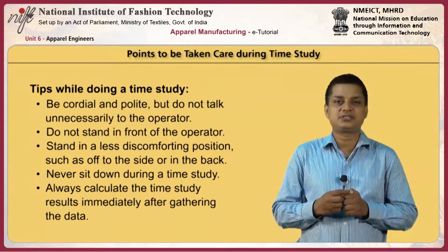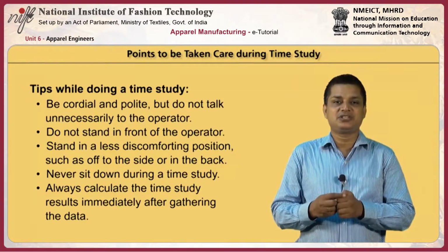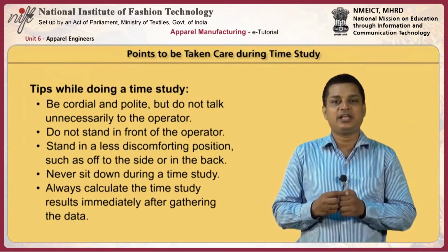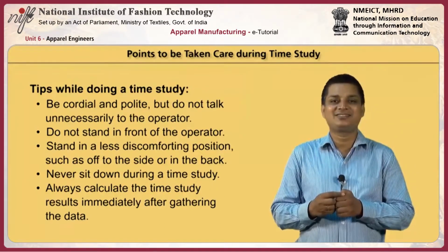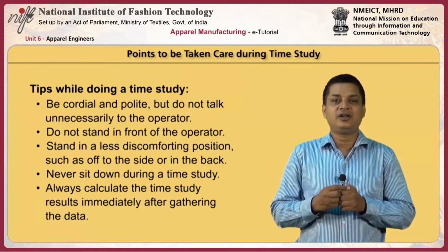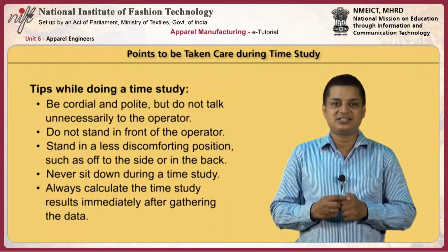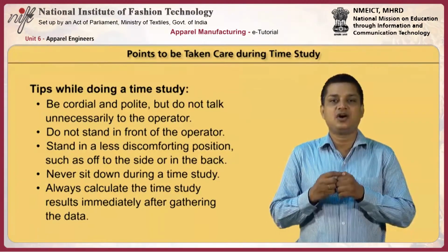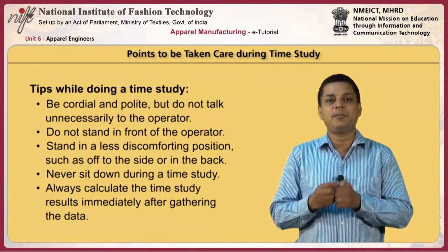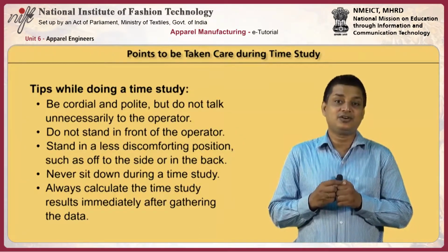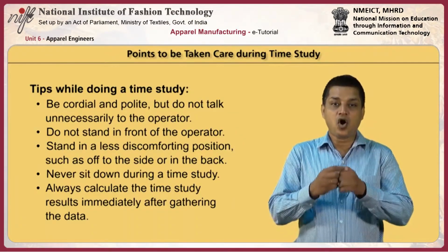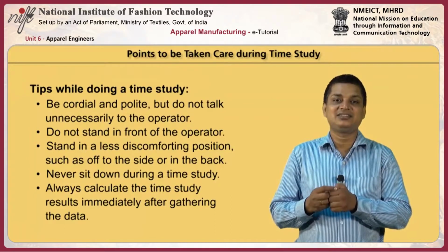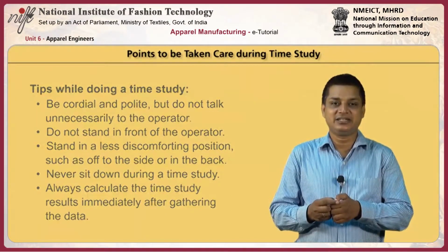Here are some tips while doing a time study. Be cordial and polite, but don't talk unnecessarily to the operator. Don't stand in front of the operator. Stand in a less discomforting position, such as off to the side or in the back. Never sit down during a time study. Always calculate the time study results immediately after gathering the data.